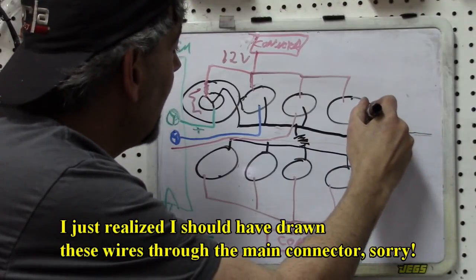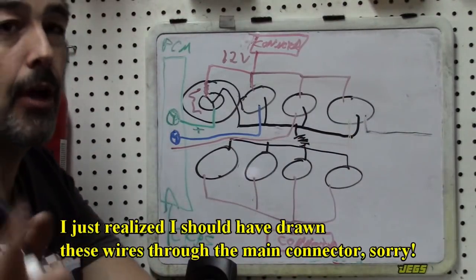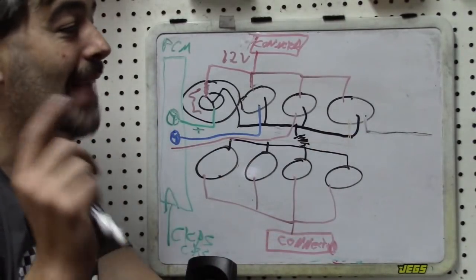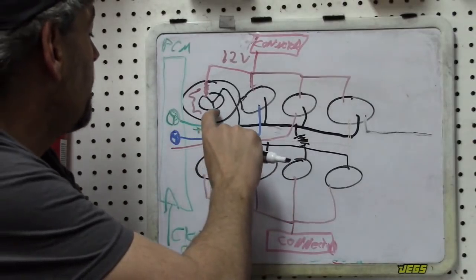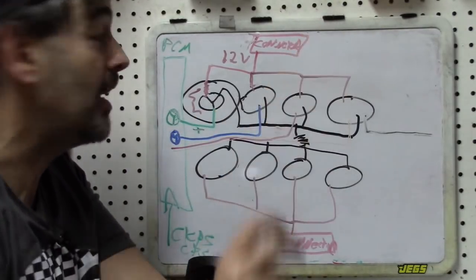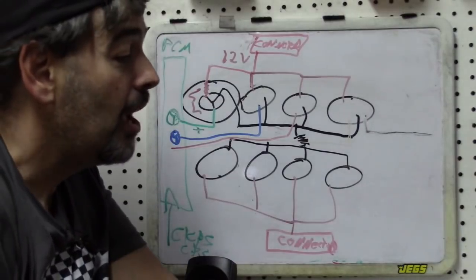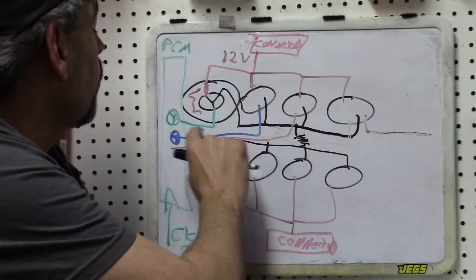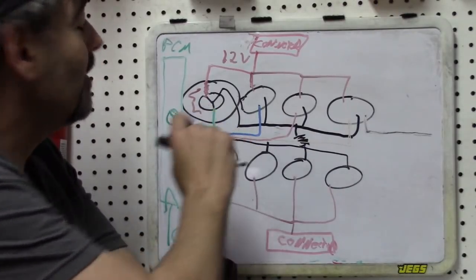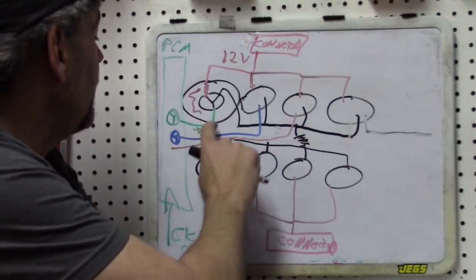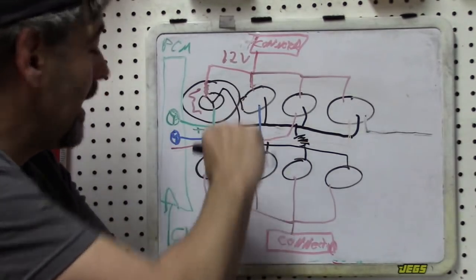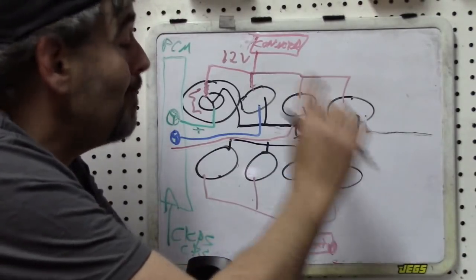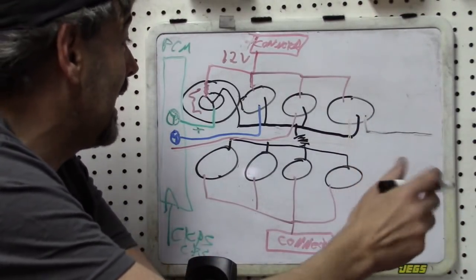We saw this in that Toyota video, and I mistakenly thought that the 4th wire would be for a PNP transistor design. We know that would not have been correct because that would have replaced the NPN base input, and in that case, we still would have had the same number of wires. You would just have this being a ground to create the activation on the transistor instead of an input to create that activation on the transistor. So it's definitely not for a PNP design.